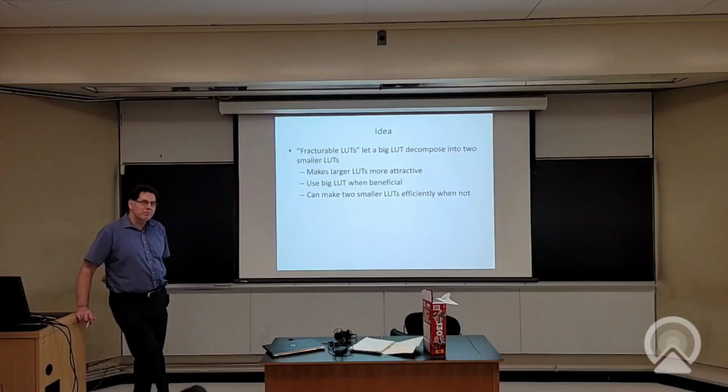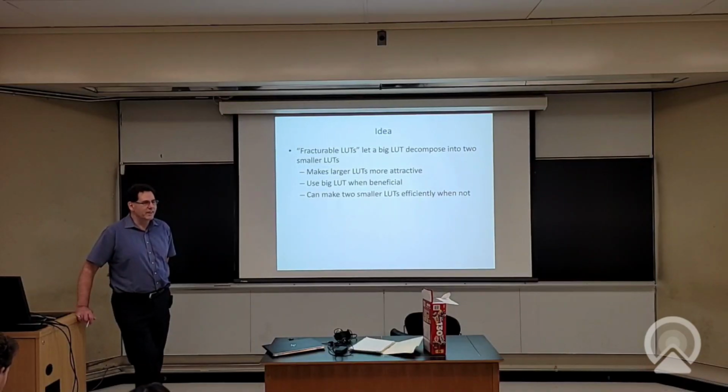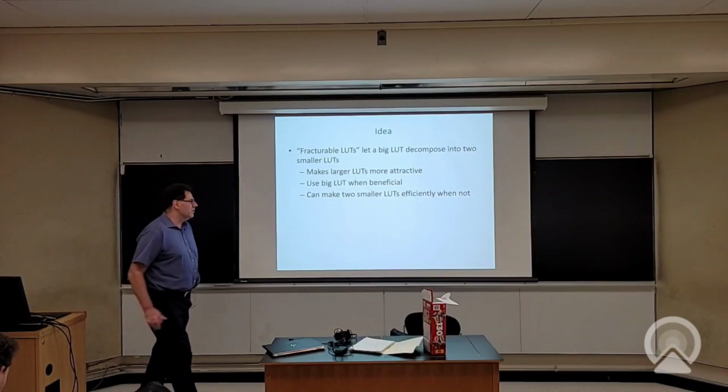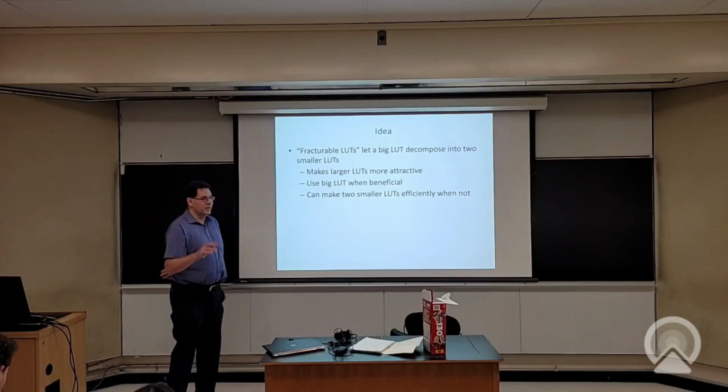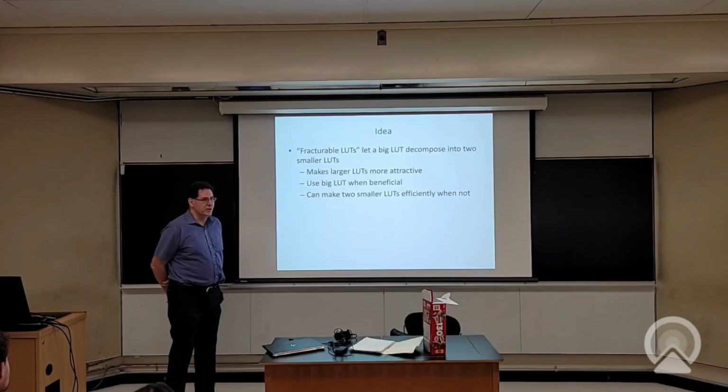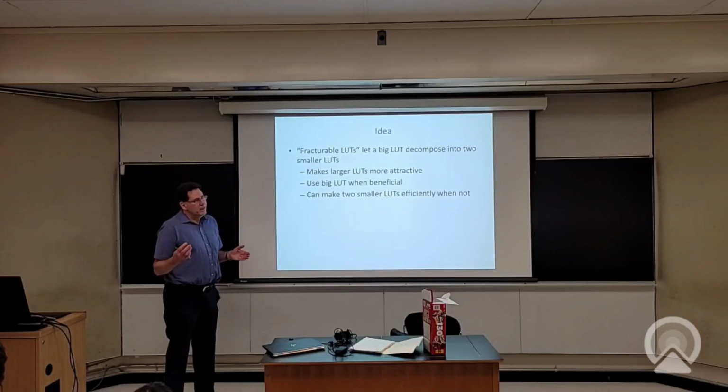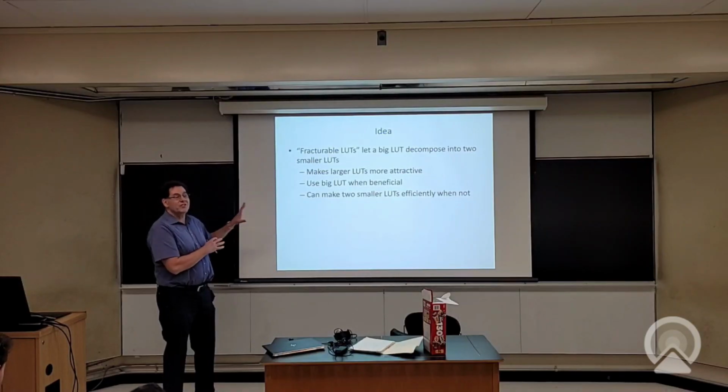There are actually some papers that I wrote with Andrew Boutros, for example, where we did that for arithmetic. You decompose the LUTs more in order to be really good at certain functions like multiplication. But for the Stratix, we only decomposed into 2 for most things. When we get to arithmetic, you'll see there's a little more decomposition going on. And that is a valid thing to do. You could decompose more.